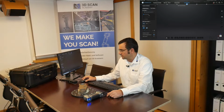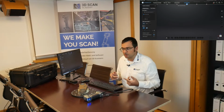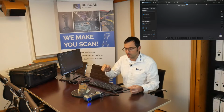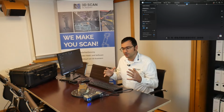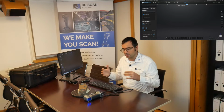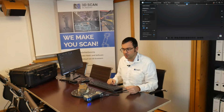Point cloud means you're scanning points from the start, and if you opt here for markers, you can pre-scan the markers. What is really cool, for optimization of your global preciseness, especially if you're scanning big parts, I would recommend to do it if you have the time. It takes more time to pass around the object 2 times, of course, but it does some kind of error compensation, calculating the same markers from different views, and it ends up normally much better.